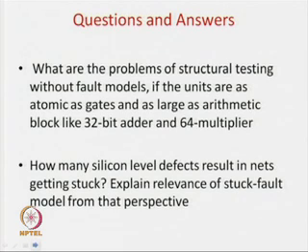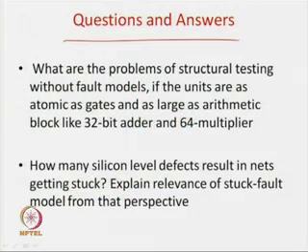So, before we finish our lecture today, we will go for the question and answers. We will be putting the questions today, and in the next lecture, just before we go to the motivation for what we have finished today, we will go for the answers of the questions. So, what are the questions? The first question you should answer is, what are the problems of structural testing without fault models? We have seen that structural testing can be done with fault models and without fault models. With fault models, what are the advantages? No requirement of extra pins, no requirement of multiplexers, no requirement of flops and registers, all those things are not required. But that is with fault models.